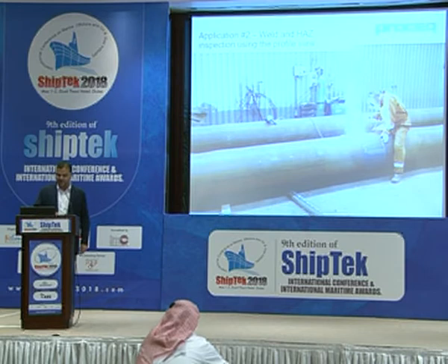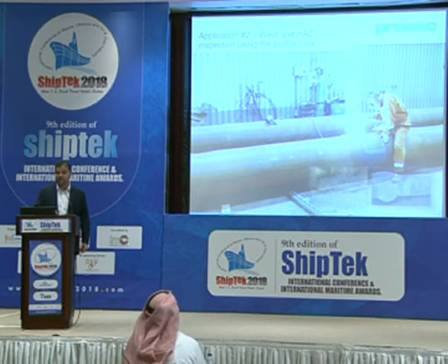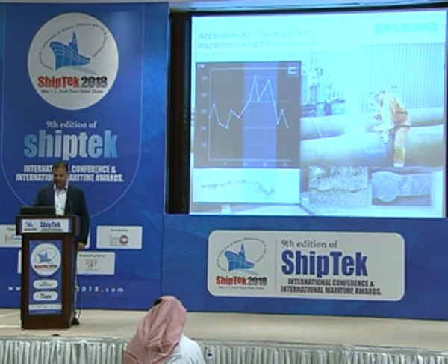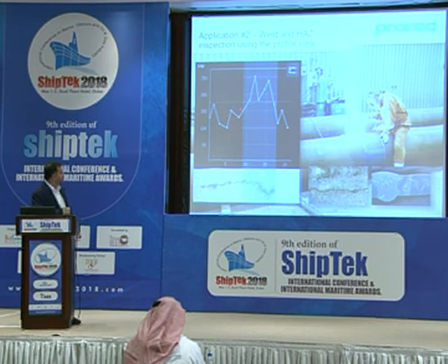Weld and HAZ inspection using the profile view. This is one of the interesting applications. So basically we can generate a hardness profile this way. Based on this, the weld, we can generate the hardness profile right on the device and save it for the reporting purpose, analysis and reporting.